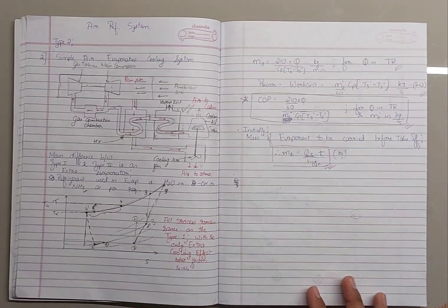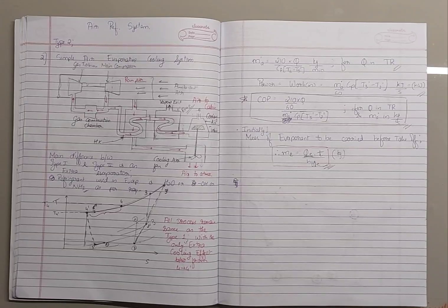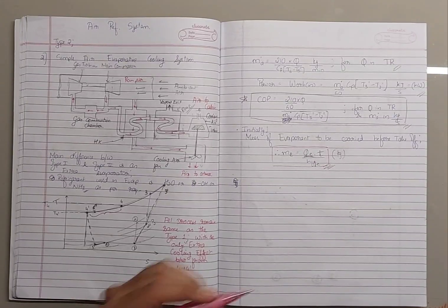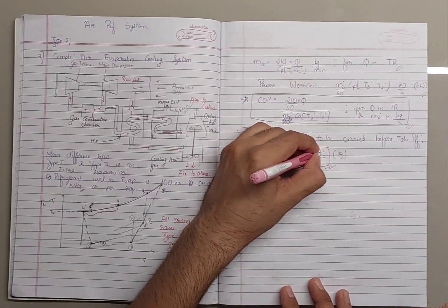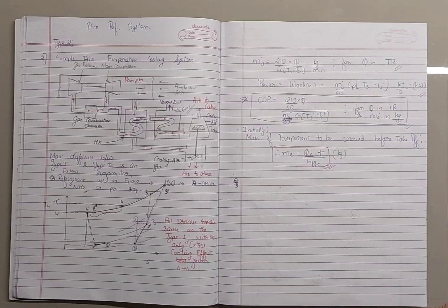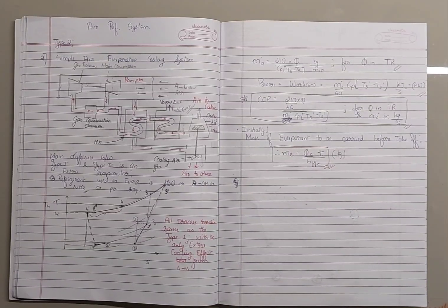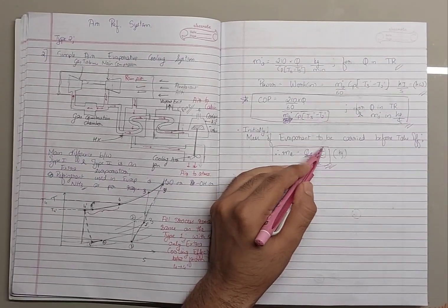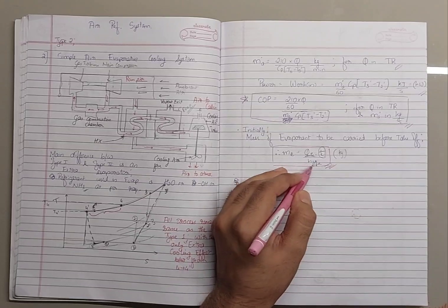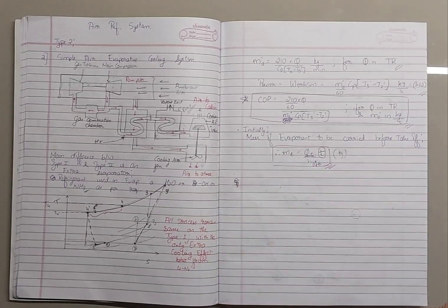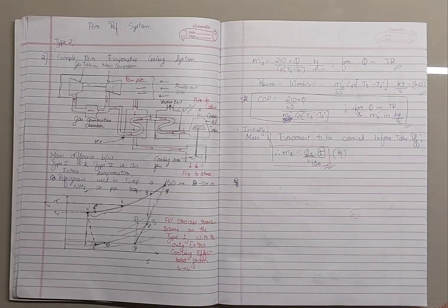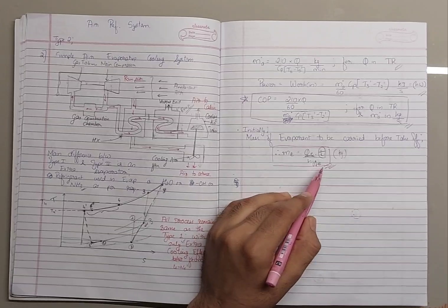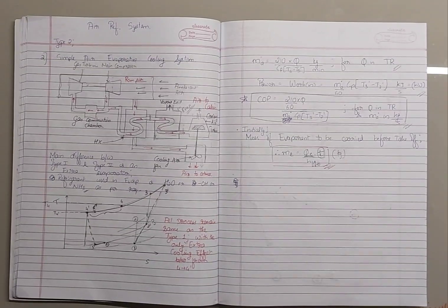QE is the heat transfer to take place in the evaporator, and the time is the time of the flight, the interval from takeoff till landing, how long the plane needs refrigeration. h_fg is the latent heat of the evaporant, the heat required for it to evaporate.